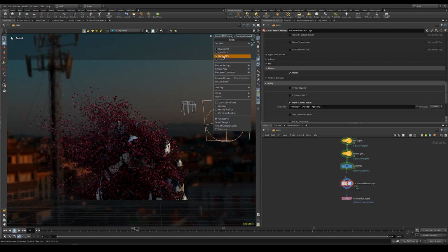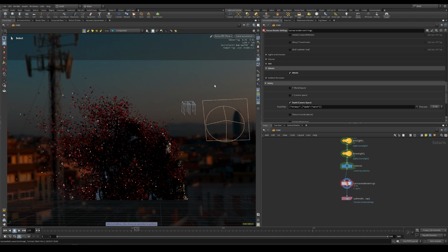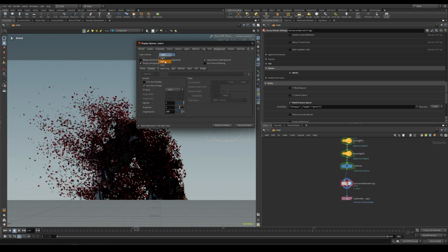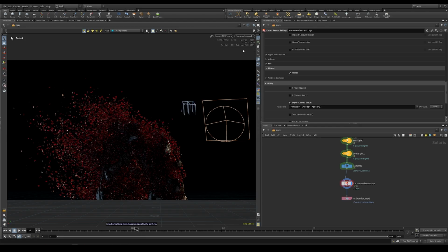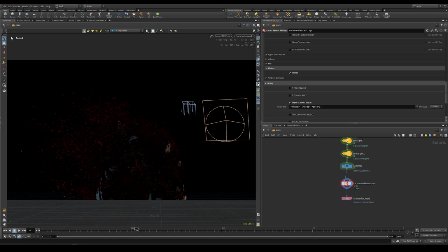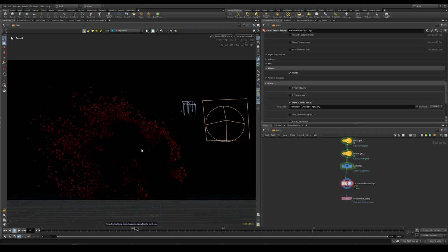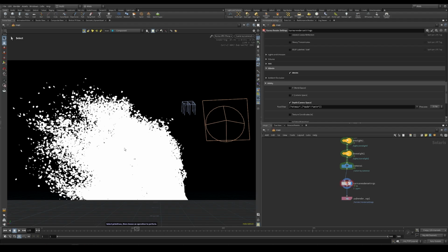So if we take a render, we can examine those single passes. Let's disable this thing and go to the dark background. So with this button you can see the single passes. So as you can see, we have the diffuse component, the reflection, then we have the subsurface scattering pass, and the depth, even if it seems wrong, is actually correct.